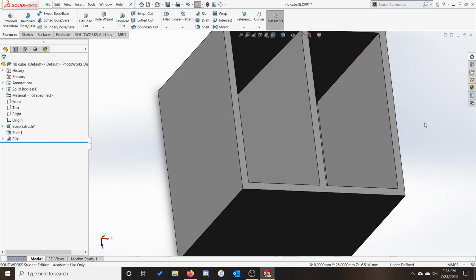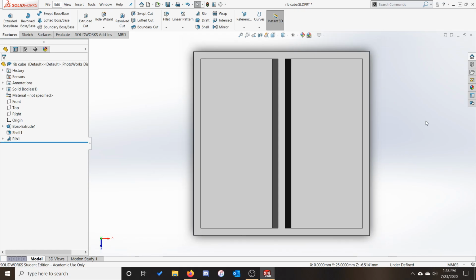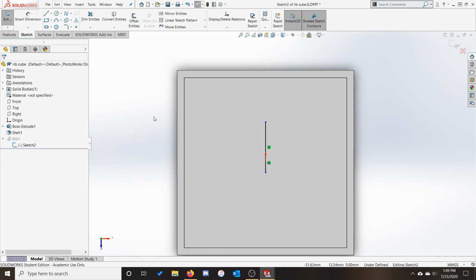This does introduce the question, though. What happens if the sketch entities go beyond the bounds of our object? If we have a sketch where the lines go outside of our object, or where there isn't anything to stop the endpoints, then we have a chance of getting the unbound RIB error.